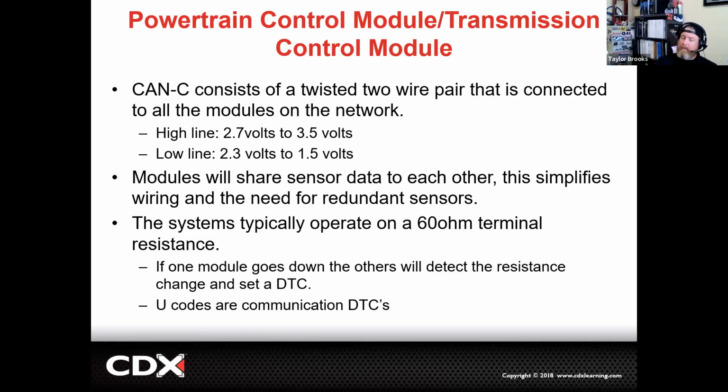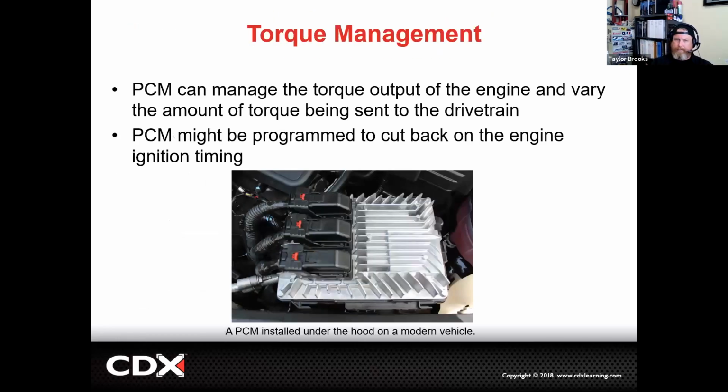I personally, when I'm diagnosing these systems, like to make my own tools out of old wiring harnesses where I will take apart connectors and find the male and female versions of the correct pins, and then make jumper leads coming off of those with an alligator clamp. That way there's no risk of you damaging the component, and you can simulate it actually being connected in the same way that the pins would have a friction fit if it was operational.